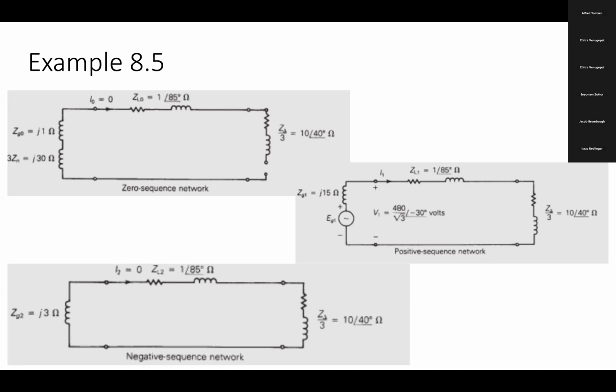The transient side of the current is usually the current coming in the negative sequence and the zero sequence, and it slowly reduces. So here, though we see the networks as three different networks, how can we look at the current by putting them together? When you are analyzing the entire fault analysis, you have to connect all three impedances, positive sequence, negative sequence, and zero sequence, either in series. All of them can go in series if it's a line to ground fault.